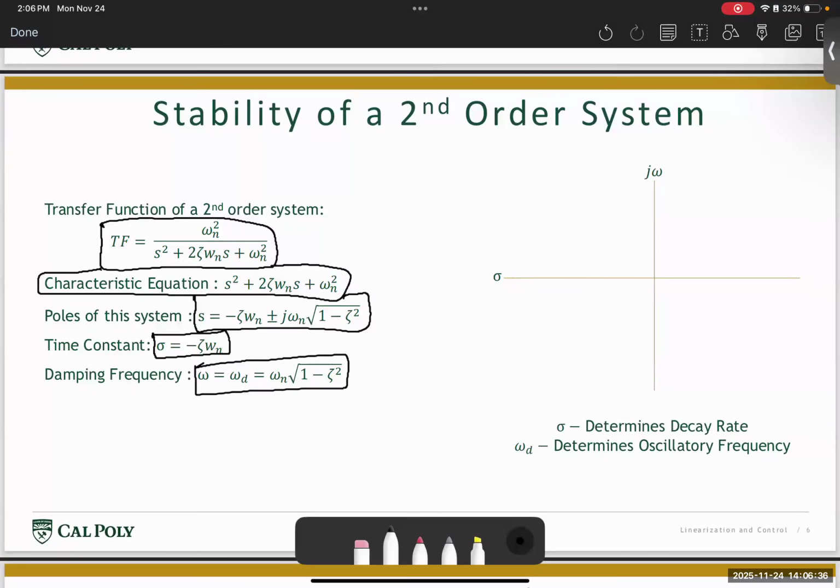Here, let's assume your aircraft is currently at 0 degree pitch, and you provide a control input to your aircraft saying that you want to pitch up by 5 degrees. So your reference signal becomes 5. This then passes into the control unit, which then generates some amount of control, which is a deflection of the control surfaces in the aircraft. This then starts to generate some amount of pitch.